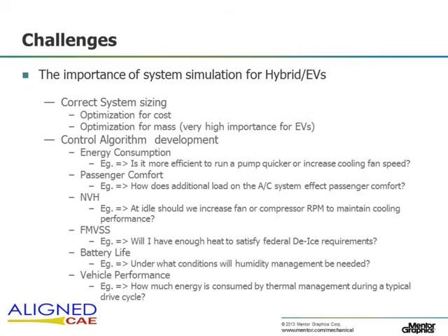So why do we want to simulate thermal management in hybrids and EVs? The first thing, which is no different to what we'll be doing with an ICE vehicle, we want to make sure that we have the correct system sizing. So we want to optimize each component for cost, and we also want to optimize each component for mass. And this is what we've done today in ICE vehicles. So we'll run a powertrain cooling simulation, make sure that we have the correctly sized radiator, cooling fan, we have the correct thermostat setting, etc., the correct size pump.